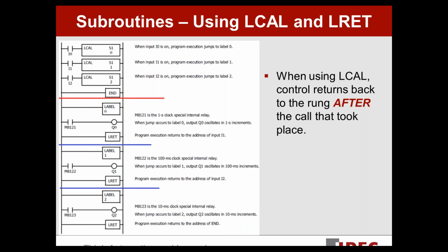label call, okay? So with an L call, if you have 3 L call instructions like we do in our main program, input 0, input 1, and input 2 can all be on at the same time, and each one of those subroutines will get executed.